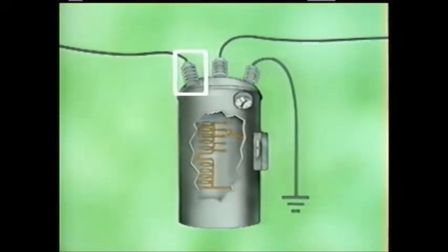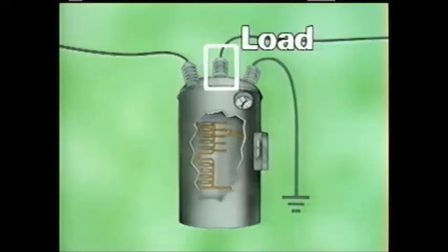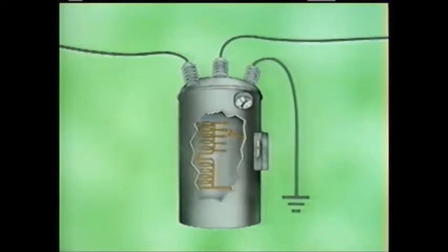This connection is usually designated as line on a regulator. This bushing connects the lead from the tap changing mechanism to the distribution line. This bushing is usually designated as load on the regulator. The voltage regulator is grounded through this 3rd bushing.